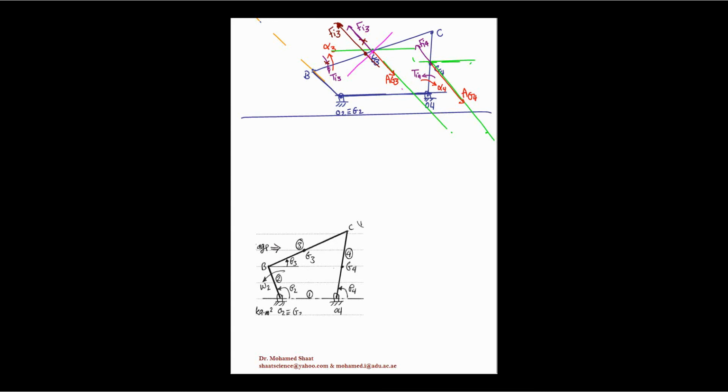But if there is more than one thing acting, like more than one force or torque, we have to combine all of these together into one resultant force, as we did for link number 3. So now link number 3 is subjected to only one force, which is the new Fi3. The original Fi3 and Ti3 we won't consider anymore. We just represented them, came up with a new force, and forgot about these two components of loading for the next steps.